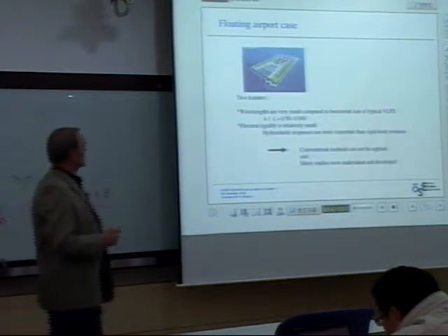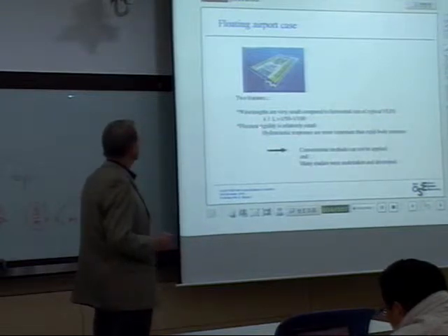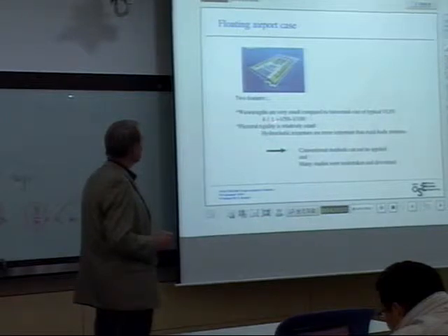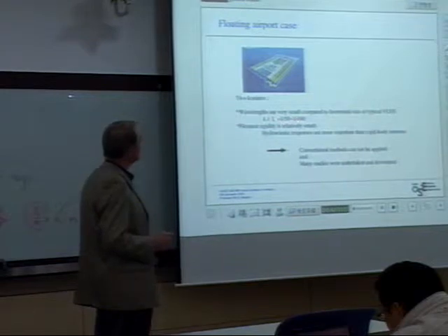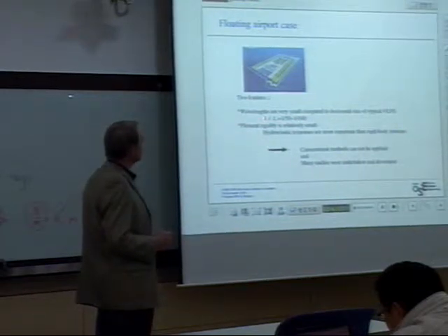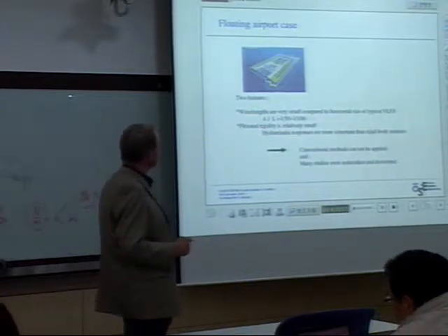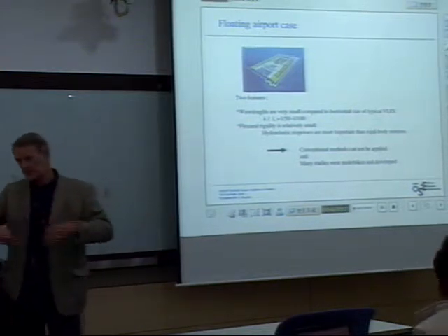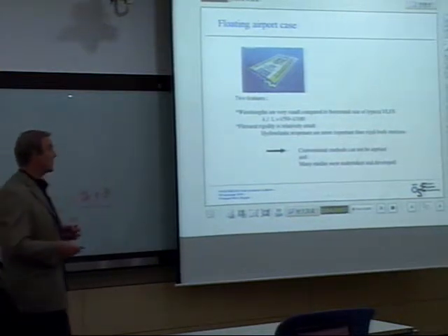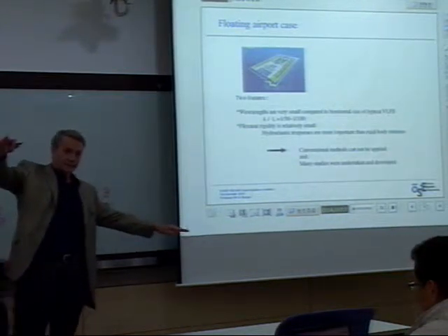So if you're talking about an airport, a very large floating structure, lambda divided by the total length of the structure is in the order of 1 to 50, 1 to 100. That's a typical stiffness characteristic. And then you see, in relation to the wavelength, you will have some elastic deformations of a structure like that, but not rigid body motions, right?